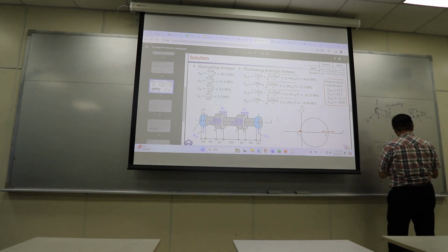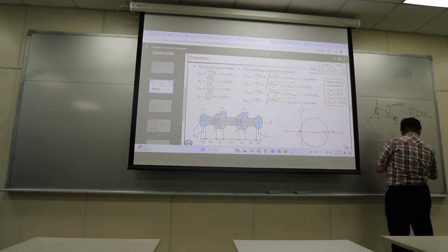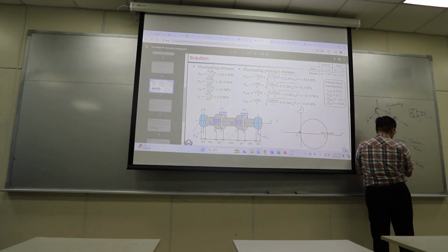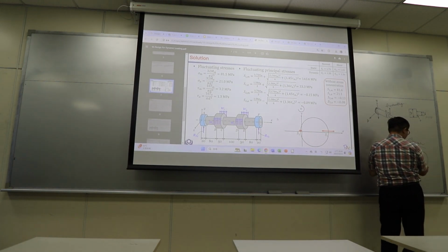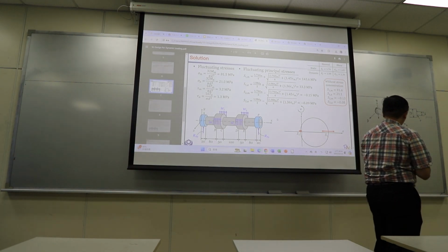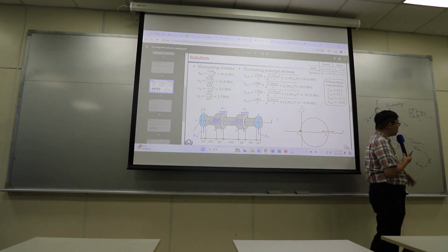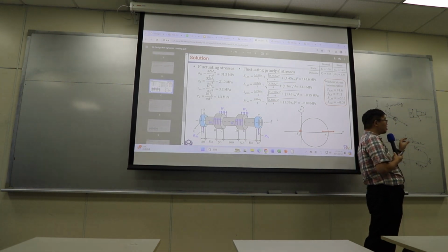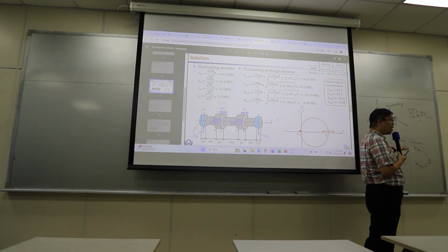Kts, yes. And this one you have Kf, this is Kfs. So to determine Kf, you need to use q. To determine Kfs, you need qs, right? And if you apply these 4 pre-multipliers to the stress and the shearing stress, what do they apply to?